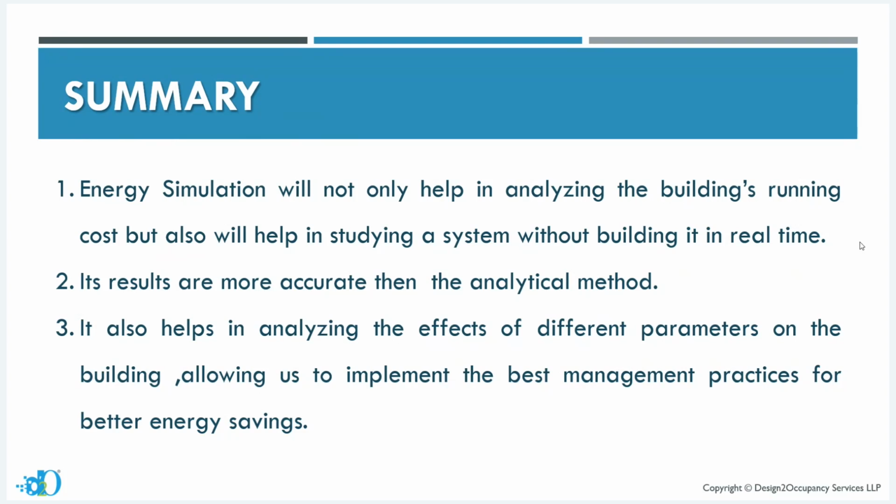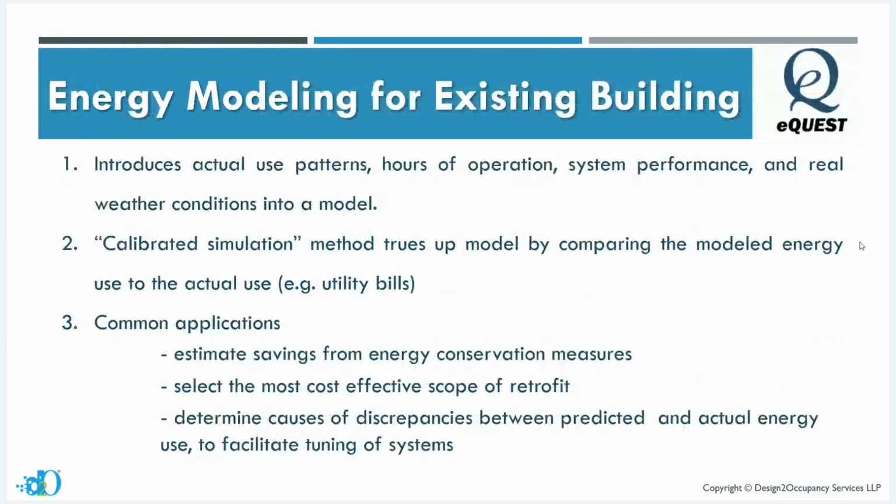But better is to do the whole building simulation, which is the second method, in which we give all the inputs of all the systems and see how much consumption is coming, and then we can compare the building with the baseline system, right? So this is the summary.